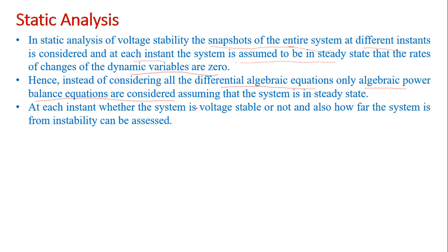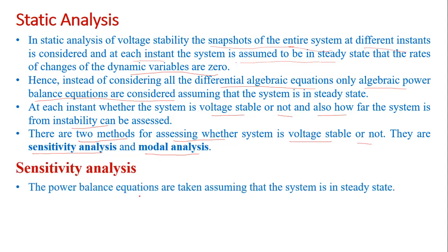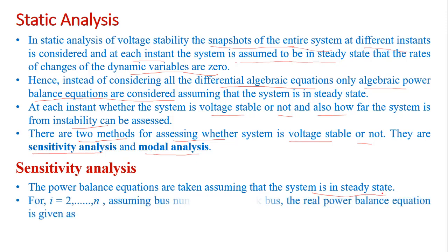At each instant, whether the system is voltage stable or not, and also how far the system is from the instability, can be assessed through this static analysis. There are two methods prescribed in the literature for assessing whether the system is voltage stable or not. One is sensitivity analysis and the other one is modal analysis. So let us first talk about the sensitivity analysis. The power balance equations are taken assuming that the system is in steady state. So now I can write the power balance equation.